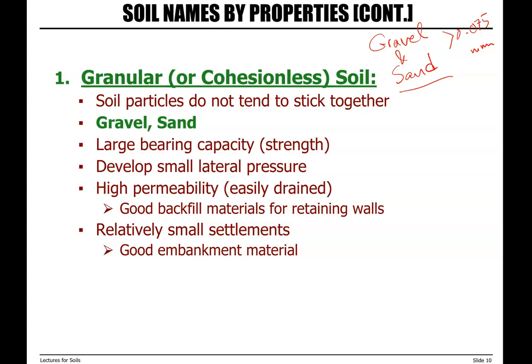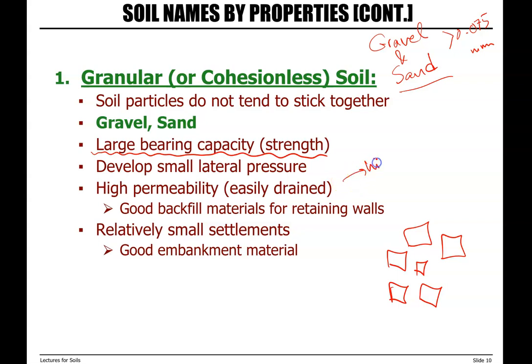Larger particles provide higher strength and higher bearing capacity. So granular soil, which is mainly gravel and sand, has larger bearing capacity or higher strength. It also develops a small lateral pressure. When we have granular soil, the particles are larger, so there will be higher void between the particles,